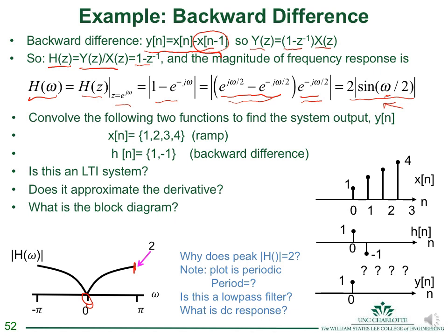And so this again is a linear time invariant system, and it looks a lot like the derivative, if you recall. If you take the Fourier transform of the derivative transfer function d over dt, it gives you 1 over j omega, or 1 over s in Laplace. Excuse me, that should be 1 over j capital omega, since that's a continuous time response. And so the plot of the magnitude of 1 over j omega would be a straight line.